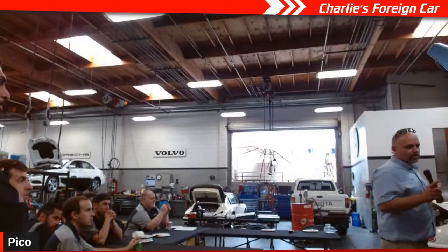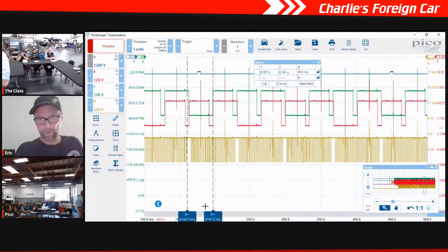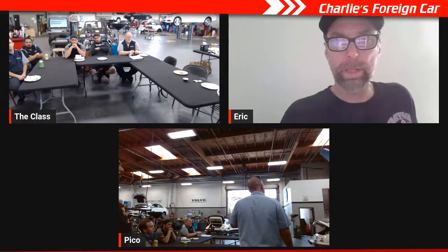So then you have a fault stored though, right? Yeah, we have a fault stored. P0014. It's just not achieving its timing mark, the exhaust cam. Well, so it's over advanced is the fault code, right? And then so when it's activated, the exhaust cam advances, correct? And the intake cam retards?